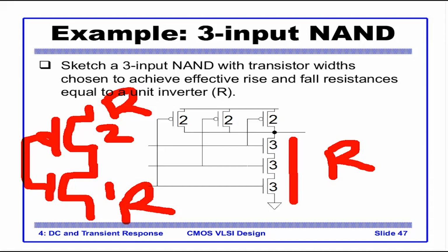If it is in parallel, you assume that only one of the PMOS would be active and calculate the width. For series, you have to make the transistor wider. For parallel, you might have to make it less wide, depending on how the parallel circuit looks. So do this for one complex gate and compare the widths.